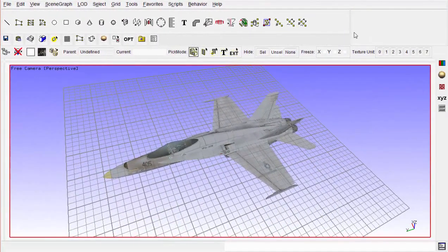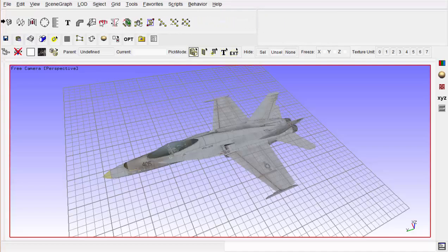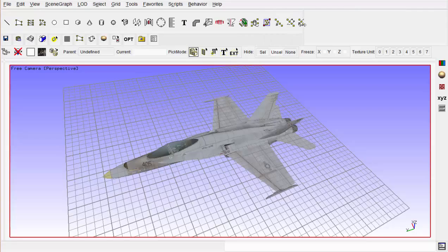Taking the Create toolbar as an example, you can see that we can left-click and drag the divider to give us more real estate. Alternatively, we can right-click and drag on the toolbar to move it left and right within its existing visible area. Reset the toolbar by clicking on the pop-up arrow bar. This space is reserved for tool-specific user interface elements.